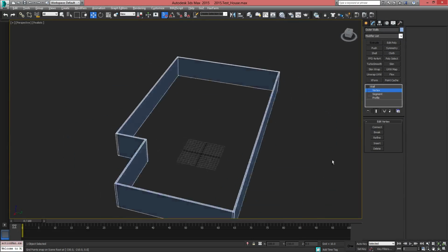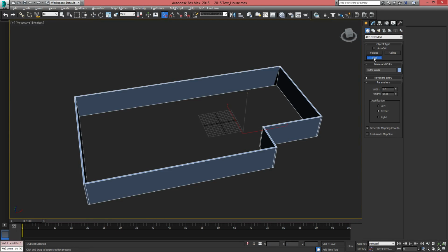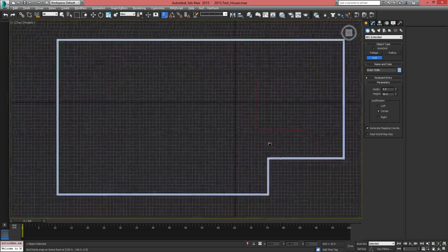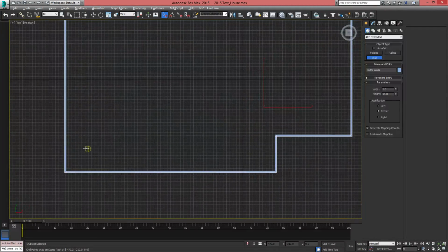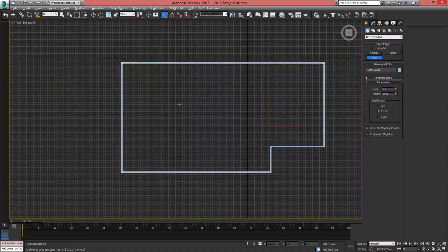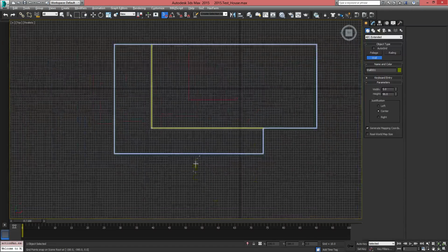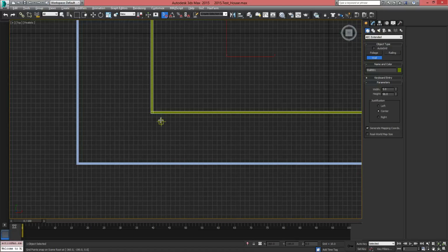I'm gonna start making the interior walls. So I'm gonna go to my wall tool again. I'm gonna start a completely different wall. So for starters, I want to have sort of an entrance area about right here, and I want to have maybe a hallway going around. So I'll make a line tool, so something like that. So I have my little entrance area with a hall, then it goes here.